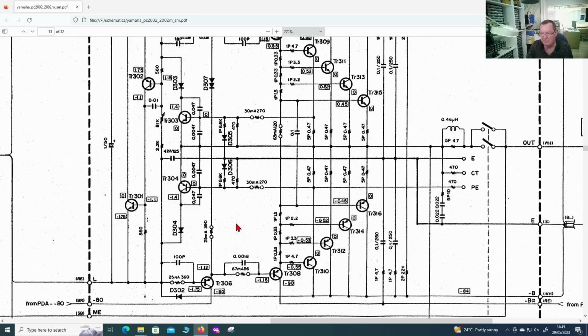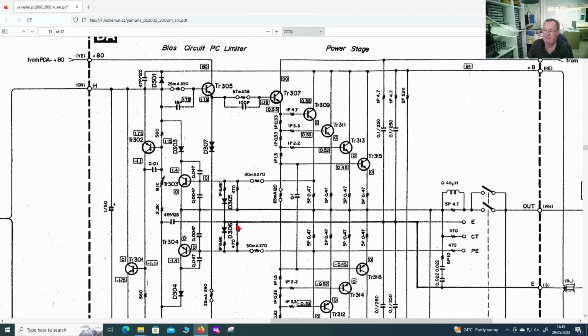I've not seen this. My gut feeling, and I am not an audio engineer, I'm a general purpose electronics fixer, is that it's done so that you reduce the quiescent current when the waveform is near or at 0. Because all these transistors, partially or just slightly turned on when there's no drive waveform, will give a certain amount of current all the time into the output. And they are cumulative, so the more transistors you have, the more quiescent current you have.